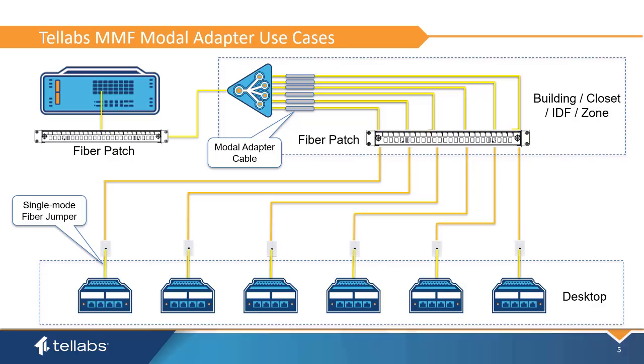New network builds should use single mode fiber cabling, not multimode fiber. Single mode supports much higher bandwidth and is better for future proofing. Modal adapter cables are only for cost effectively upgrading existing multimode fiber installations.